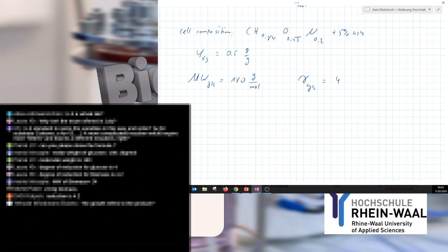Growth doesn't refer to the product. Growth refers to the biomass. You will see it if we calculate it. So in the equation before, what is given on the board is just glucose plus oxygen gives carbon dioxide plus water. But in our general equation with growth, we also have, of course, a term for the biomass, because you grow the biomass. So you compare this chemical formula without the term of biomass with the term with biomass, and we now calculate the oxygen demand using our electron balance.